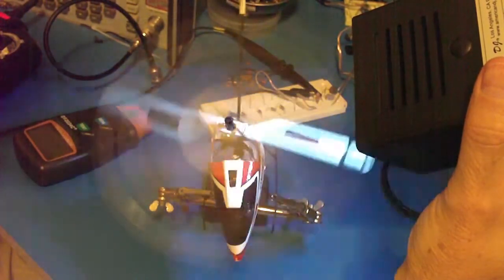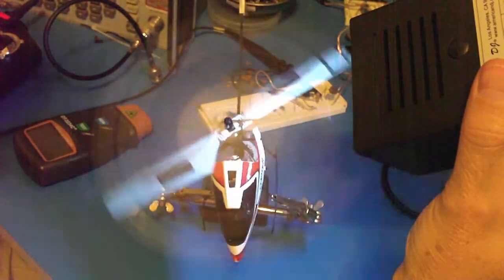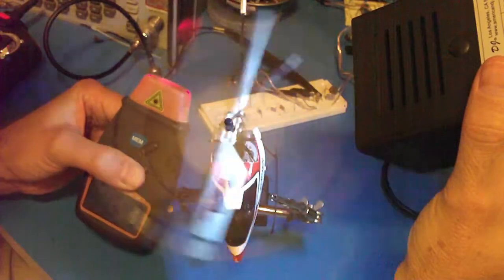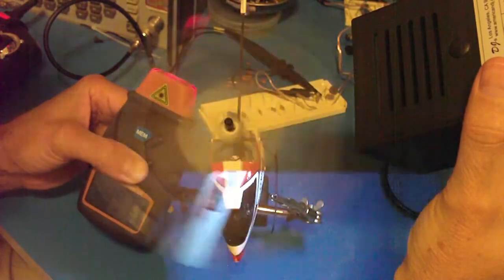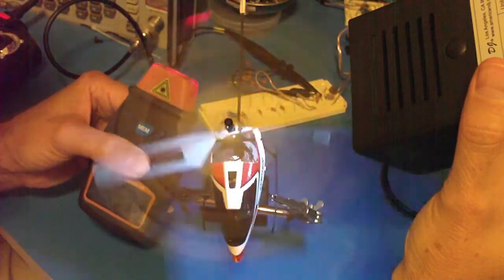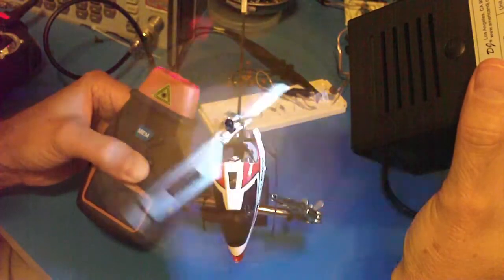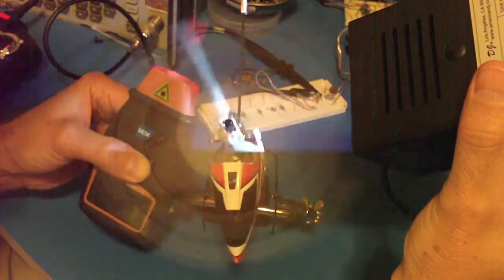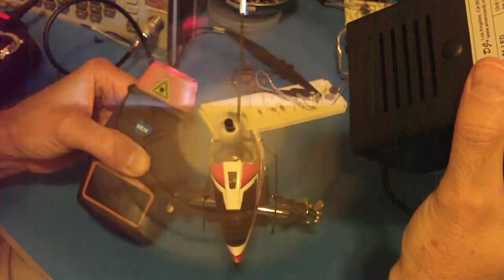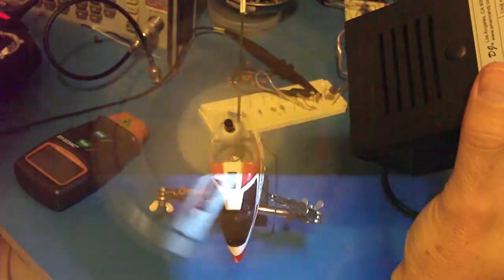So now we should see a reflector on both tips because it'll be turning 3.5 times per sample, and there we go. Reflector on each tip, and we should see 5250 RPM, 5220 something. It looks like it's turning backwards slowly. So 5170, 5160. Again, it's hard to get a reading that's stable because it gets a little noisy at these rates. 5140. It's about there, 5100 something.